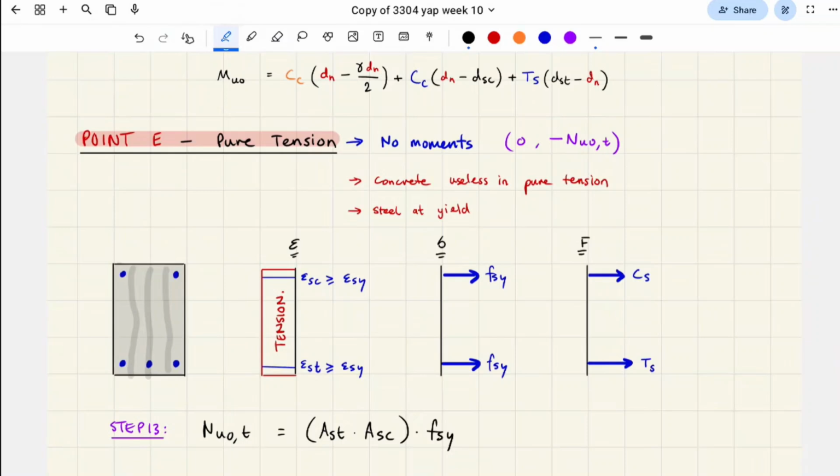The concrete itself. Okay, what's a good thing to think about? Think of it like bread. You know, crusty bread. Concrete's kind of like that. It's brittle, right? So if you pull it, it'll have very minimal tension. In fact, in the standards, we consider it 0 because it's literally so little. And you're right in thinking that it does have a little bit of strength, but it's not due to the concrete. It's actually due to the steel.